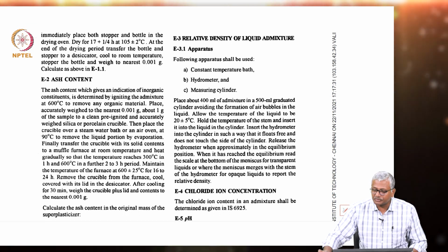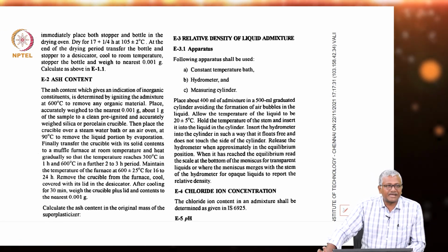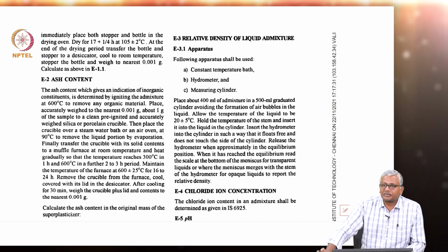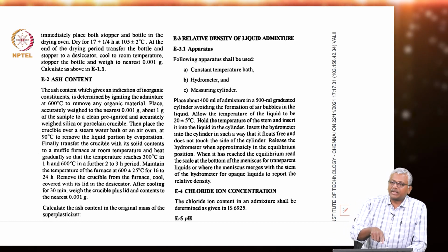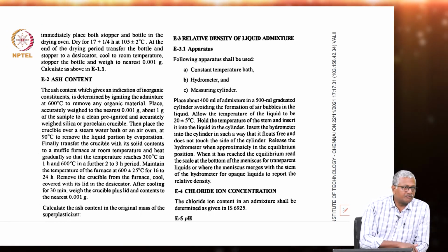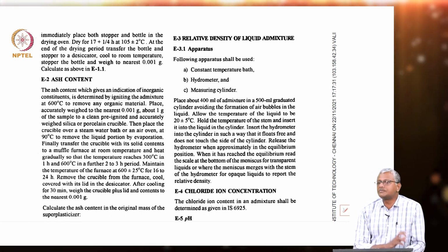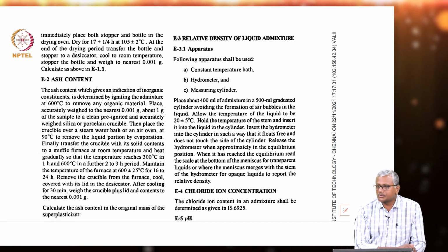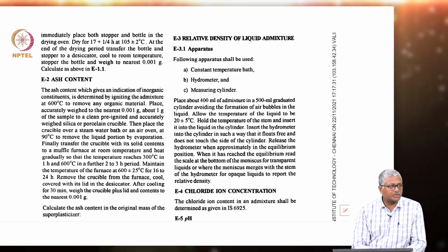So the idea is to pay attention to the details that are given there, because very often on sites the kind of quality test that we do may or may not be adequate for the purposes of actually assessing the properties of the admixture. In addition to that, you may also want to do the marsh cone test, which we discussed earlier. When it's a super plasticizer, it's always better to do the marsh cone test, because that helps you assess very quickly what is the compatibility of this admixture with the cement that you're using for the project. Or if the cement source changes, again marsh cone is very important to be done.